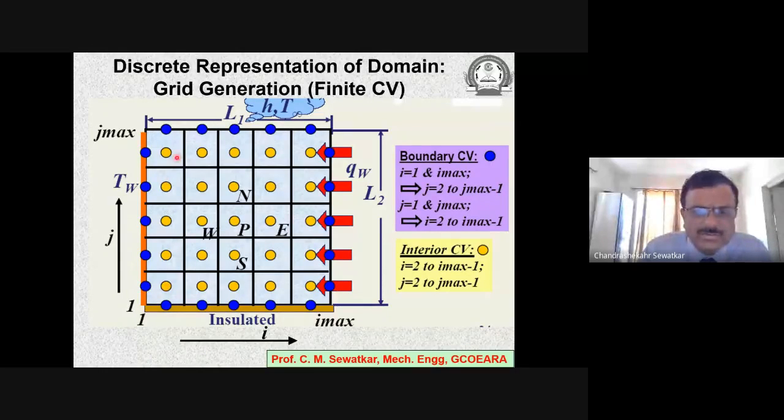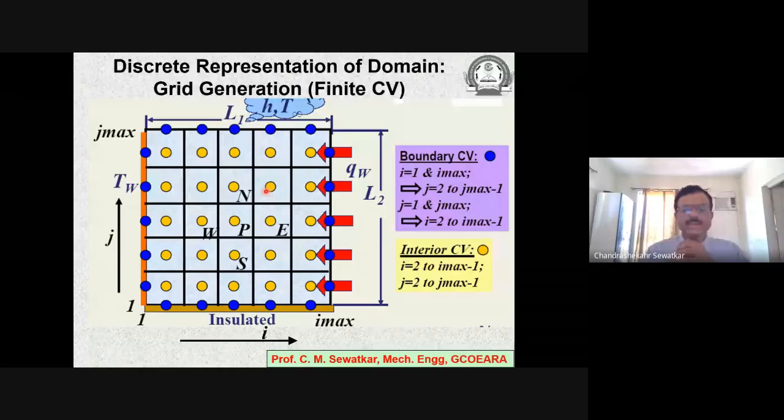So thus I can scroll through. Once I scroll through, I get some new values of all the cell centers. Then I can use those new values for determining next new values for all the points. Again, next. We can keep on doing iteration. So carrying out these iterations is essentially called a simulation. So after every iteration, we get new values of phi p's. And when the values obtained during a consecutive iteration are the same, we can say that we have arrived at the solution.